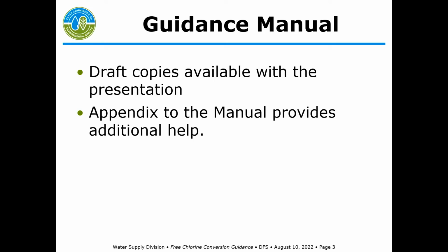What's important about the guidance manual, besides what I'm going to talk about today, if you look at the appendix, there is a bunch of information, some charts and stuff, to help you figure out, for instance, is your existing equipment, say chlorine injection equipment, sized to do a breakpoint chlorination? If you're a booster plant or you have a booster plant, you're receiving water that already has chloramines in it. Most of the times those booster plants don't have enough chlorine injection capacity to actually take that water through breakpoint. So that's a real helpful tool in the back to help you work through those issues there.